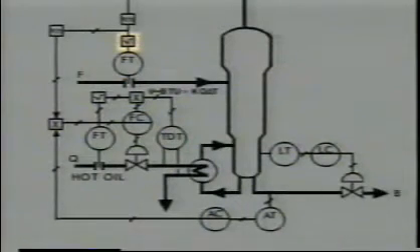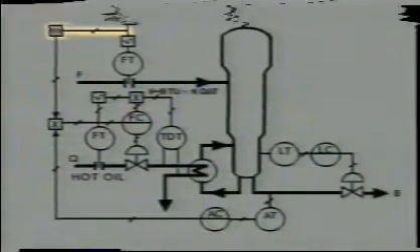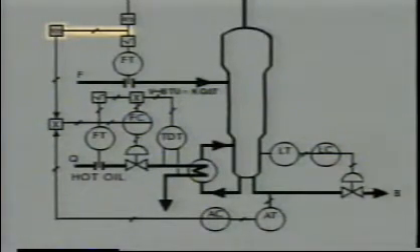The square root is extracted from this signal, and the linearized signal goes to a time function block. Here, the output signal will equal the input flow value averaged over a period of time. The signal then goes to the multiplier function.